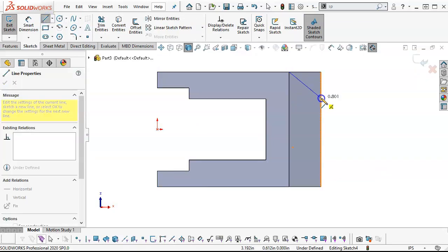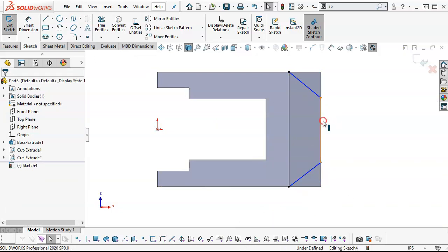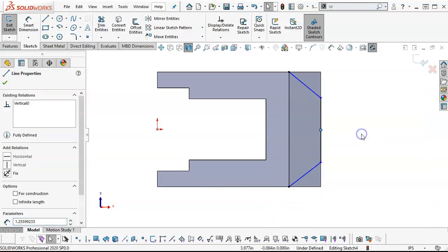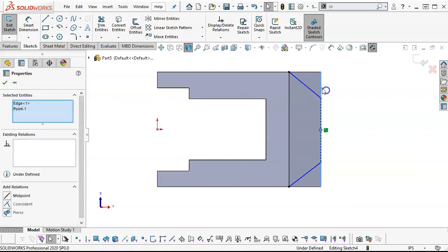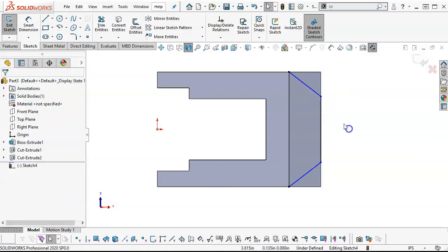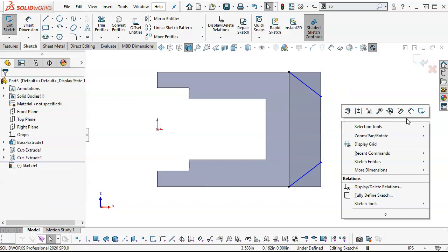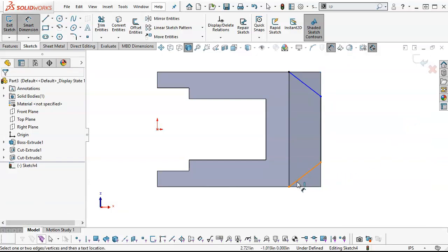Since that edge is now driving the 0.62, I'll just pick that up as a coincident. And we're going to be symmetrical, so if I select the midpoint, go into the control on the edge, set those to midpoint, then we can set our angle of 45 degrees.